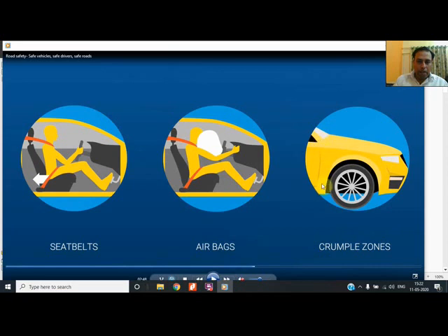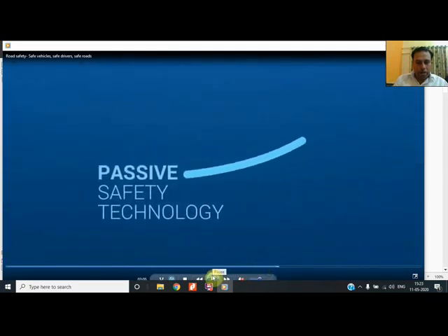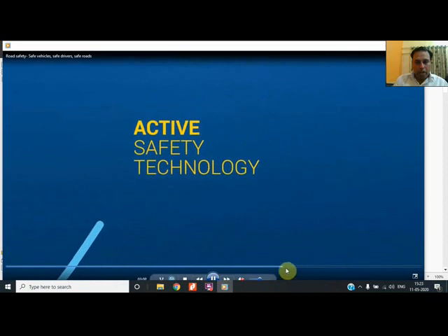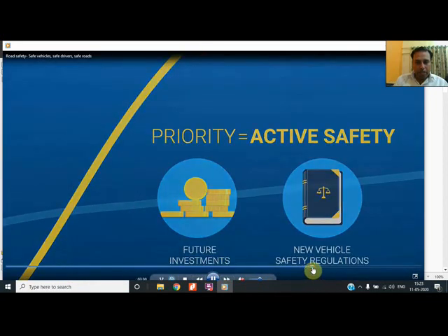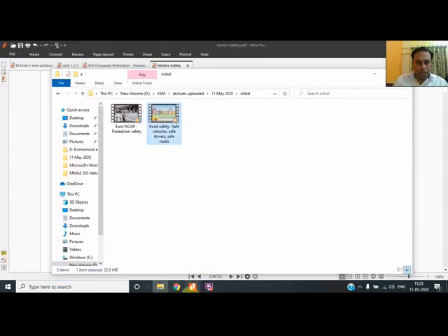And the driver cabin, just behind the heat shield, meaning the engine compartment and the heat shield wall, the impact should not pierce into the compartment, meaning it should not go beyond this limit. So this type of passive safety came into play. And the head restraint, the slide portion you are seeing over here, is also an important feature for passive safety when the accident has already taken place. So we'll cover one by one what happens when the accident has already taken place and what happens when the accident hasn't taken place. So there are two types of systems we will cover in today's lecture.